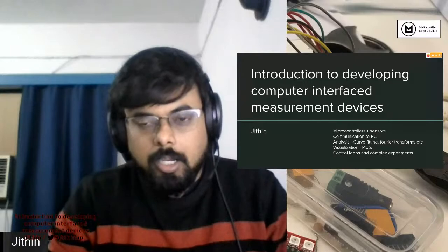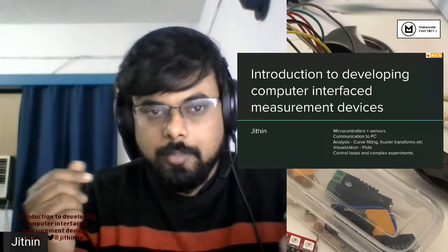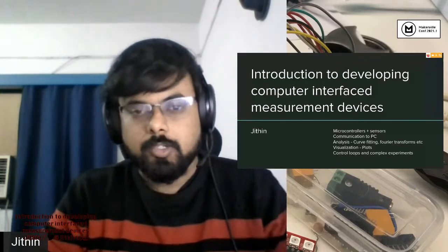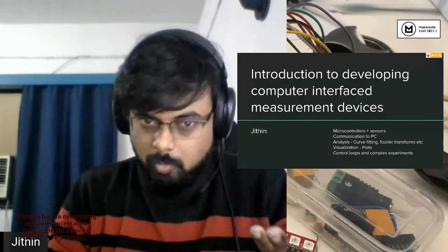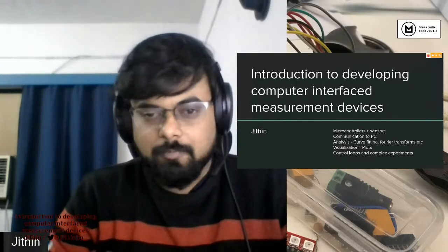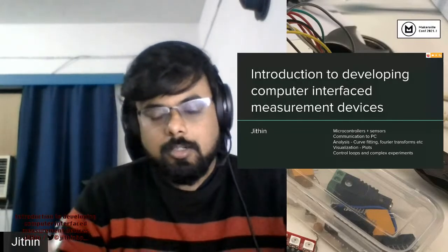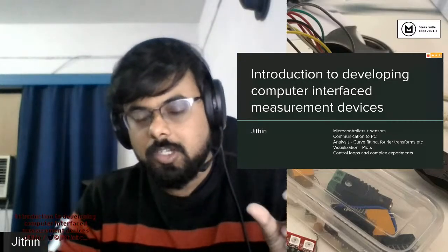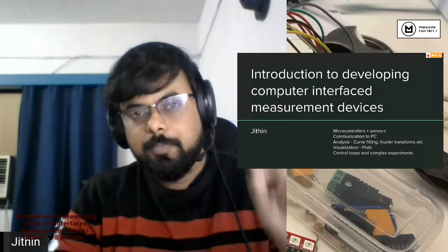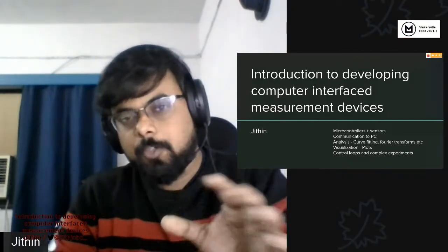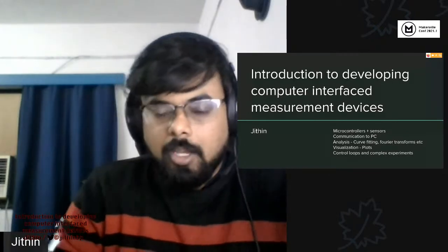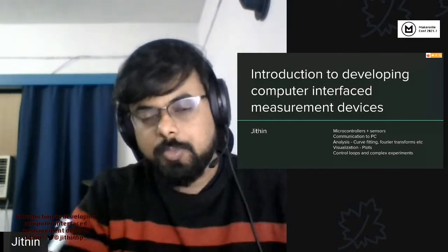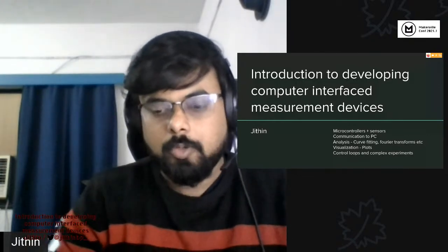And to demonstrate, I'll be taking two instruments which I've been working on closely. One is QtPy, which is a very elementary project designed to teach how to program microcontrollers. Taking one look at the photo, you're probably thinking this is some sort of dev board, which it is, but the difference it has from, let's say, an Arduino is that the bootloader is slightly more functional, wherein you can use a connected PC to tweak each register in real time without compiling and uploading code. And there are also some layers which allow you to connect sensors to this and directly get data onto a PC without actually compiling and uploading code of your own.